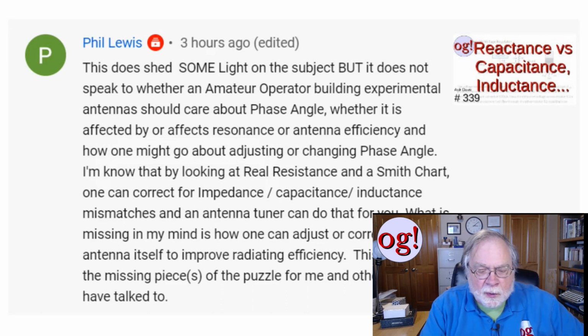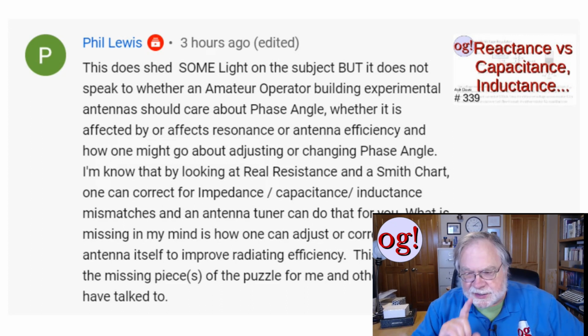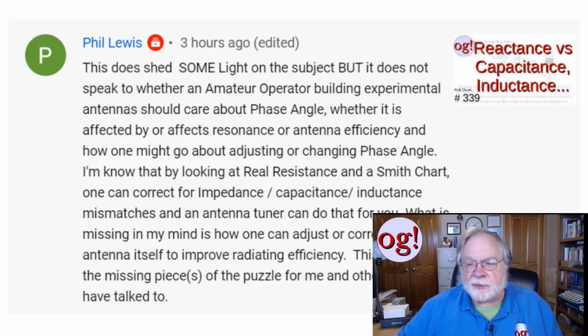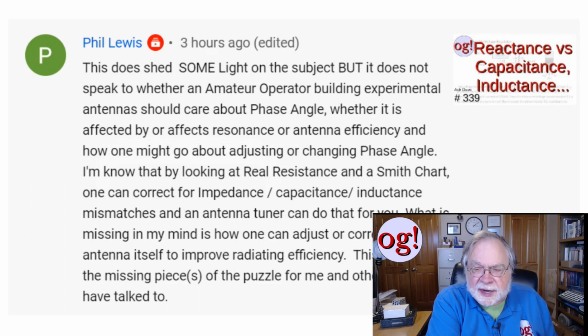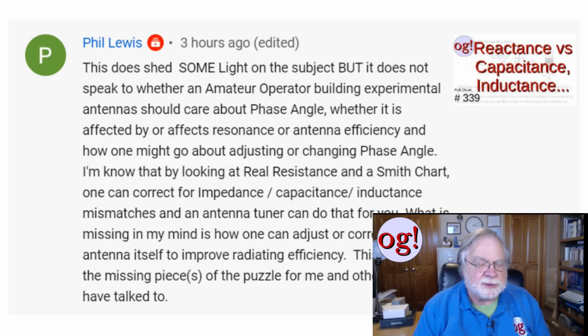So what some people do, if they're looking at a single frequency, is use their antenna analyzer to calculate the length of the coax to be exactly 1/2 wavelength, taking into account the velocity factor and so on. Then if you connect that to your antenna and then connect that to your analyzer, what you measure at the end of that half wave, or full wave, or any multiple of a half wave, will be exactly the impedance of the antenna, and then you can try little things to bring it in.